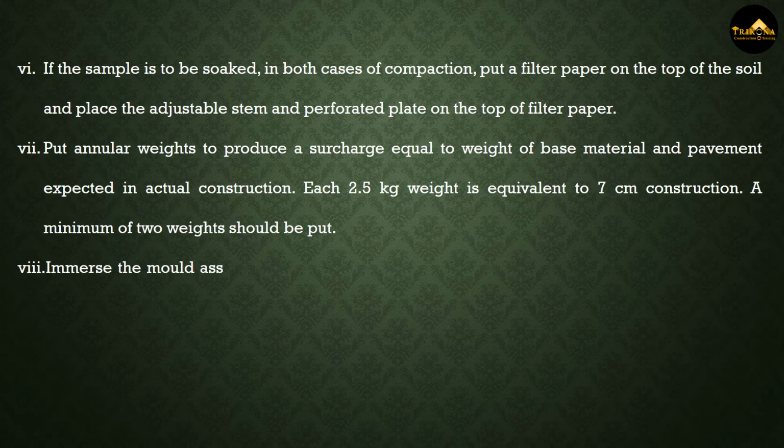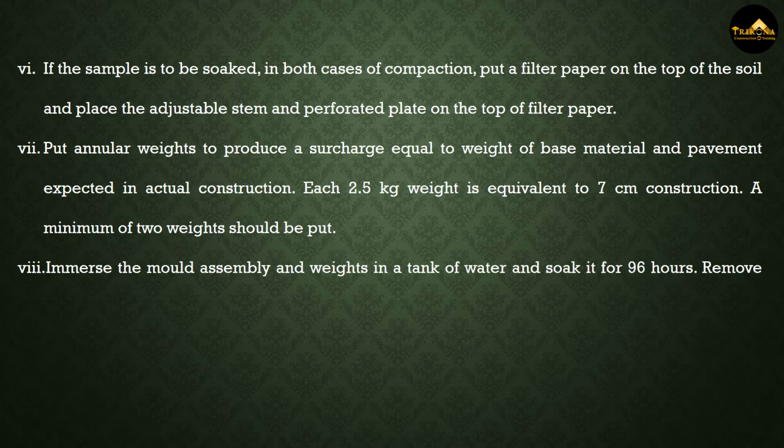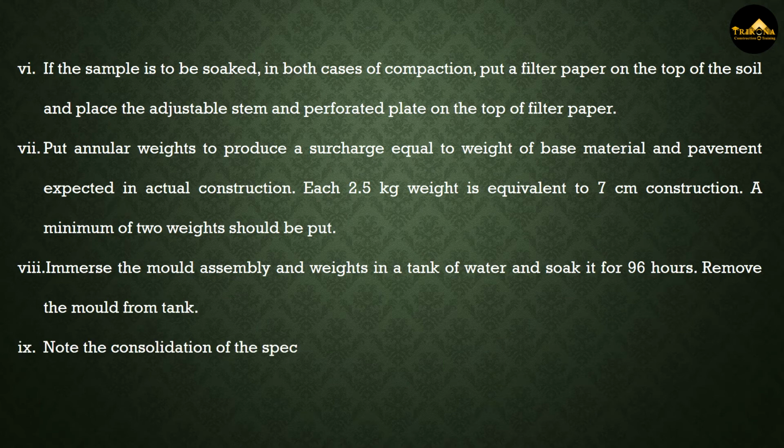Immerse the mold assembly and weights in a tank of water and soak it for 96 hours. Remove the mold from the tank. Note the consolidation of the specimen.